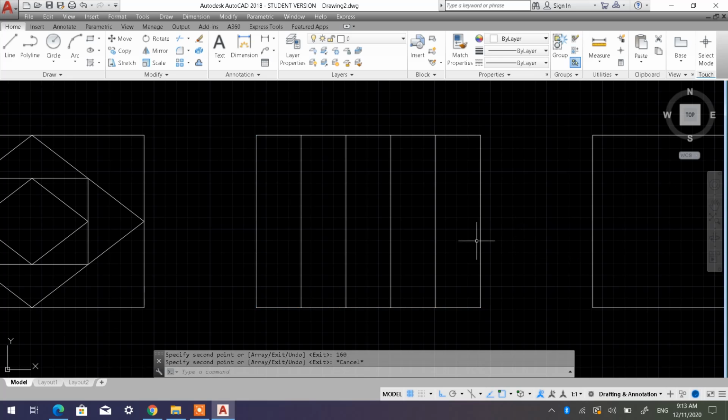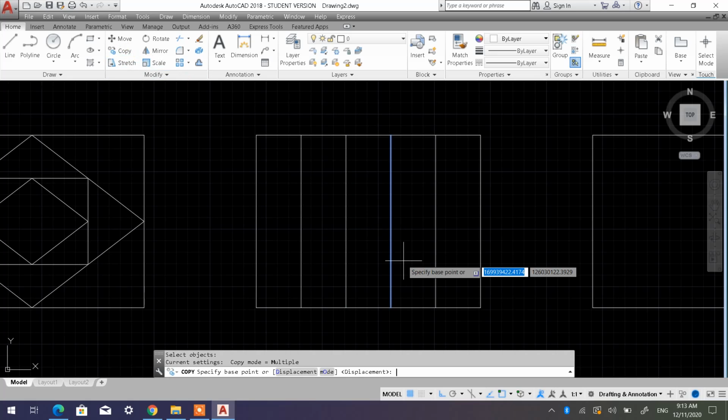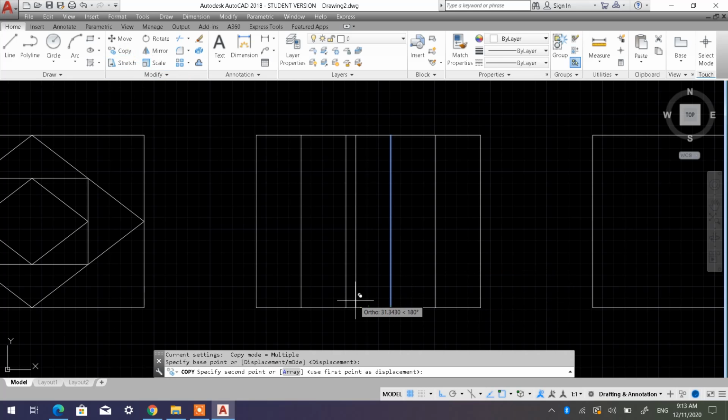So when you want to exit from this sketch, just press escape. Okay, so it means that if you want to copy, let's say I want to copy here, I want to make just 20. In the middle here, I want to make just 20 here. I want to take this one, this or this line. Okay, either is fine, we can choose either one. So let's say I want to copy this line, enter, then I start from here, let's say I start from here as the endpoint, and I bring my cursor to here, so I want to make 20. So just press 2, 0, then enter.